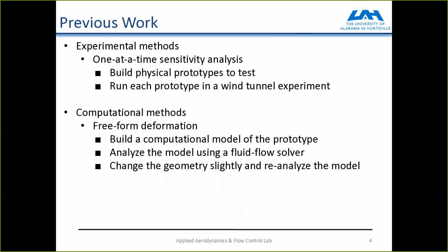Computationally, a lot of people use a method called free-form deformation, which is where you build a computational model of the prototype, you analyze it using a fluid flow solver like Star CCM+, or ANSYS, or CFX, and many others out there. And then from that solution that you get from that software, you'll slightly change the geometry and then reanalyze it again, and you'll keep doing that process until you get a good solution. That good solution is defined by the user.